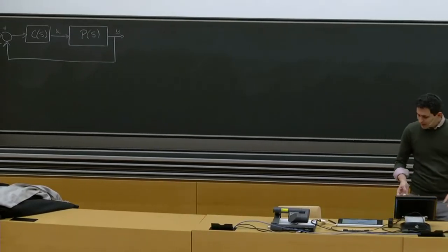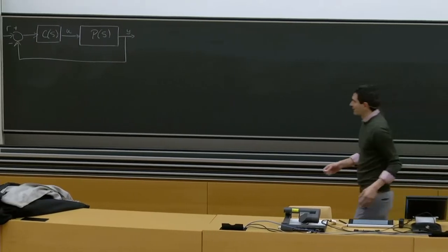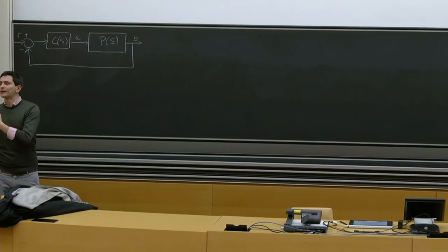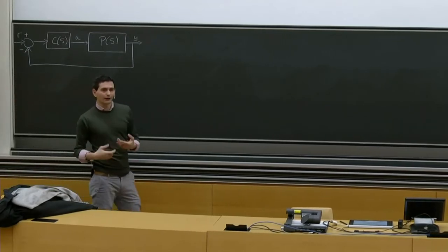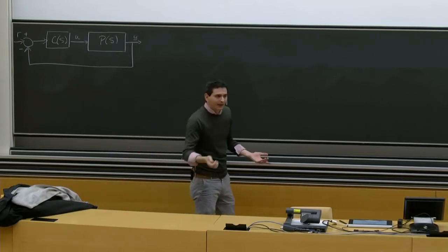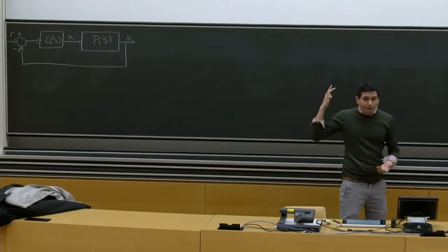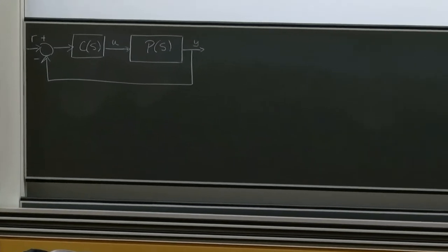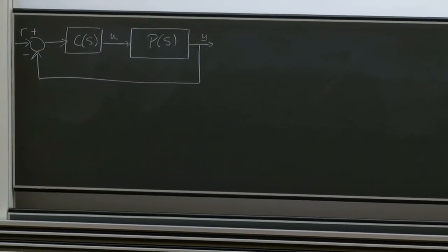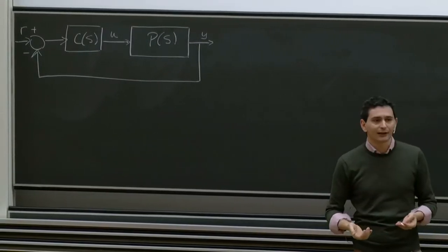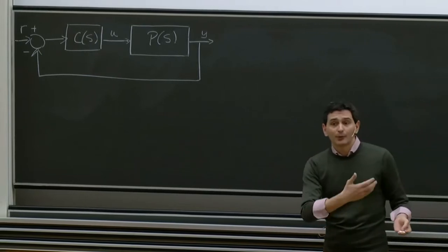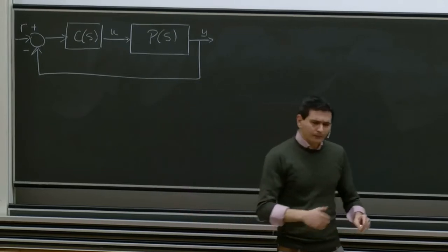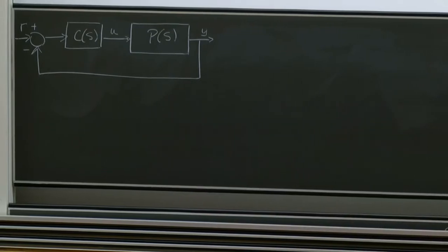Okay, so, throughout the class, we saw many ways to first define what desirable means, right? I mean, you want the system to do something, but what should it be? So we identified 3 really important things to do for a controller. The first one is get your system to be stable. What does stable mean? Stable means it won't explode. Or in more technical terms, as time passes, the output of the system or any of its internal states will not diverge, it will not go to infinity. So that's the first most important concern.